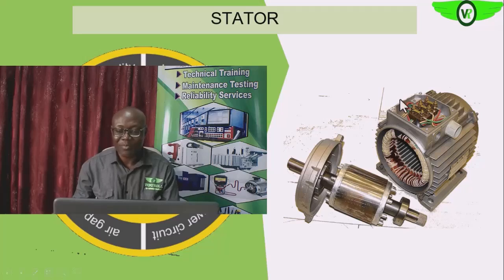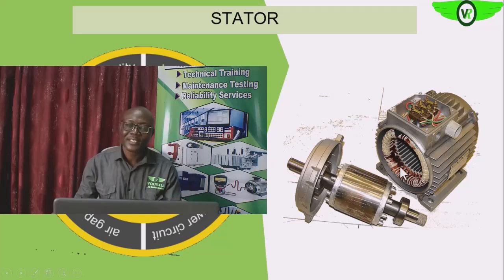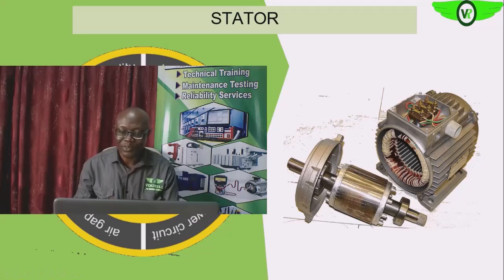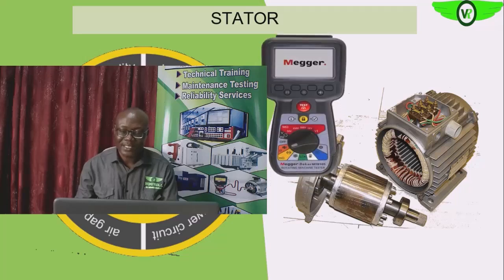Remember, unbalance in the resistance can also introduce voltage unbalance that will eventually affect the operations of the electric motor. So that is what we will do. You can check out our training on resistance tests and low resistance winding resistance tests on electric motors in our earlier section.